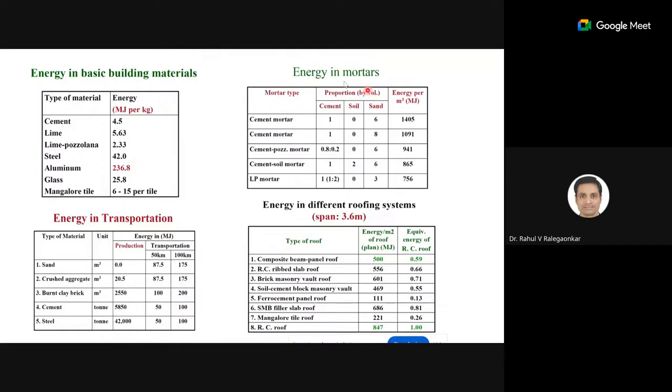On a larger scale, when we start comparing, these are significant values that were supported or given by some of the manufacturers. Deliberately, I have removed the brand names because of confidentiality. But having said that, we have certain numbers available with us, and when you come up with some mix proportion, how to calculate the embodied energy is very simple, because in terms of proportioning we know per cubic meter how much the impact is going to be.